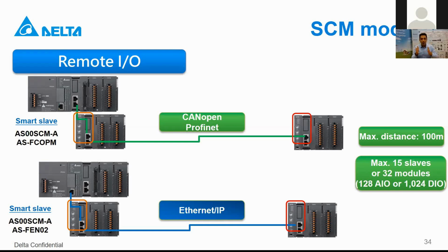So in the hardware config, you see which address is assigned. From that table, you can understand. But I can say that it's going respectively. So let's say that you have one input here, which is X0 channel, right? Then the other input is in the remote I/O, and it goes with X1, and the second one goes with X2. So it's going respectively. But it's also possible to check in the hardware config. Okay, I hope that answers your question.